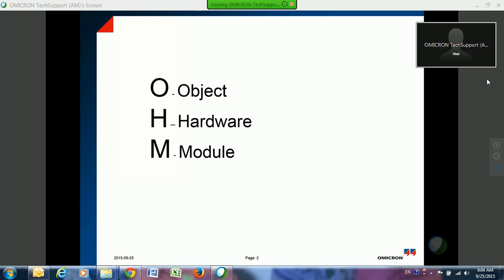The second part is hardware. Hardware is very important because you need to configure your test set to be able to use the proper currents that you want to be using. It allows you to set up whether you're going to do 3 or 6 individual currents, or you can combine currents together to get different values, from basically 75 amps max to 128 amps if you're using a CMC 356.